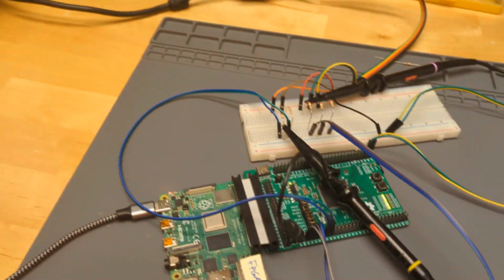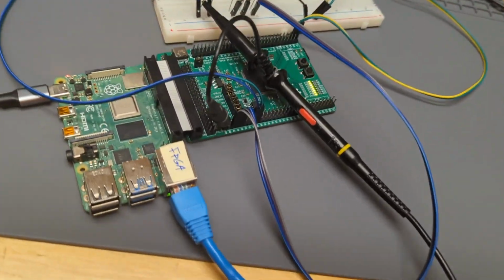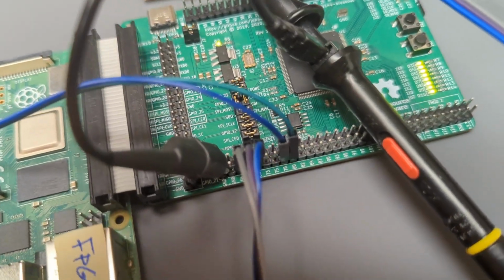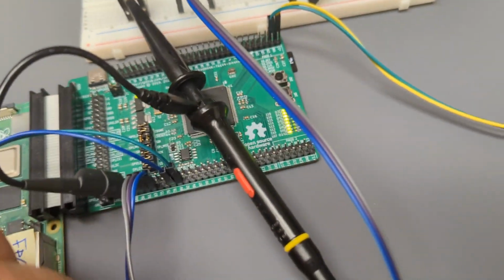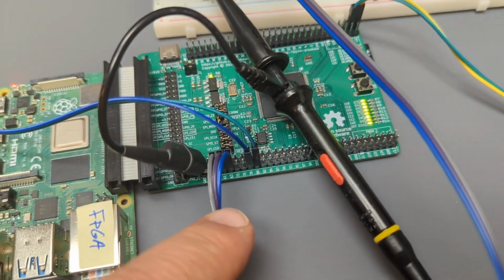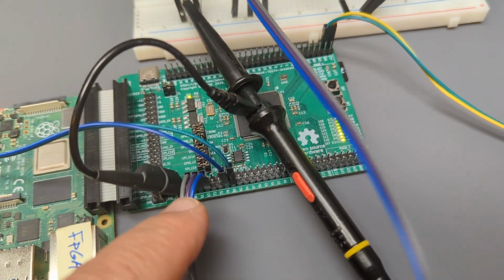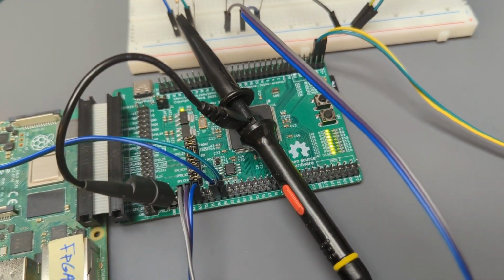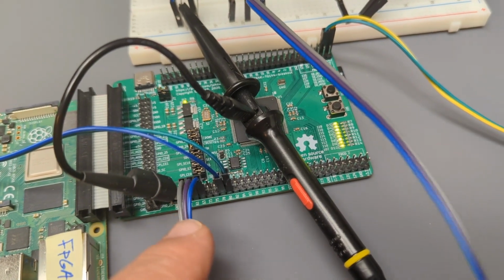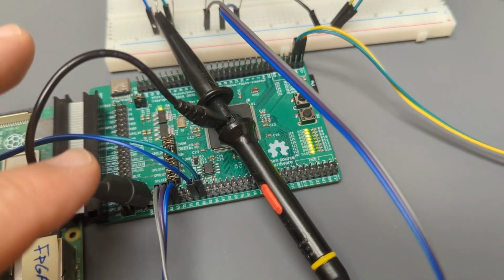What does the other button do? Did I hook up button 2? No, I did not. We just looked at the code. Of course I didn't. So there it is. Now you can see I've got these jumper cables here from these pins on the bottom row. If you look at the PCF file, the first 3 pins on the bottom row that are not ground, this is going to my scope ground obviously, are going to be the R, G and B values. Then I skip 2 pins, and this is your horizontal and vertical sync.